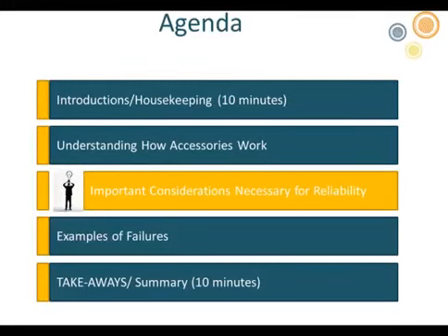For example, how deep of a knife cut at the semicon spec, and how big of a semicon tab will cause a failure? As I mentioned, the higher you go in voltage, the less significant a defect will cause more of a problem with it. So we've done some experimenting, and I know I haven't done it exactly to see exactly what caused a failure, but I have done some with as minimum as 10 mil deep knife cut in the insulation, and even with 10 mils deep, it will fail almost immediately at 35 kV.